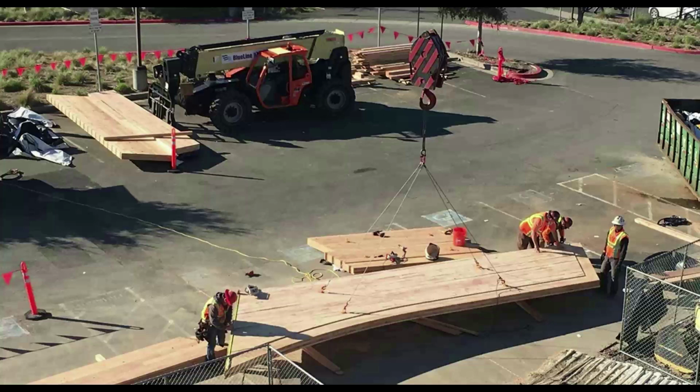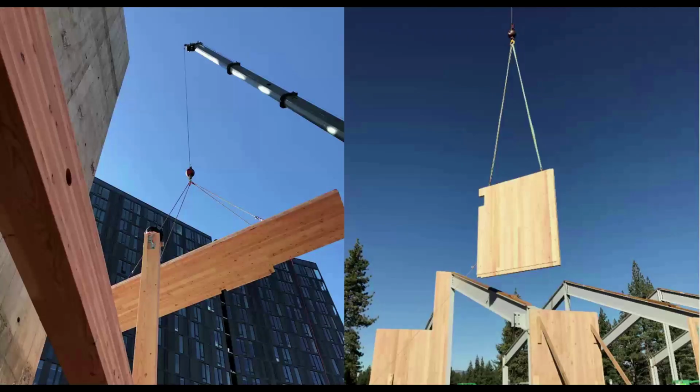This used yokes, which are essentially, like I said, a flat plate with 2 structural wood screws and a D-ring, 4 pick points. Oftentimes these pick points are located on the shop drawings. A couple of pretty pictures of some panels being flown into place. The one on the left was Side Yard. The one on the right was the MBEF building in Truckee, California.